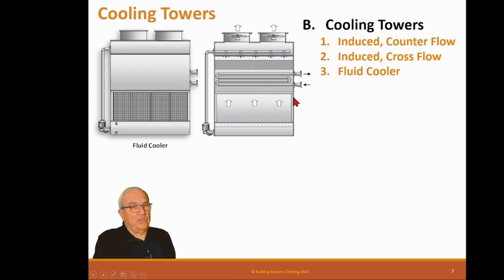So another way you can do this is you can actually put the heat exchanger out here in a flat plate heat exchanger and put some pumps. It seems like it'd be more expensive, but number one, it's 30% less operating cost. This heat exchanger and the fill adds more air resistance, so these towers are not as efficient. These fluid coolers are not as efficient as a tower. So you can save some money by putting a separate heat exchanger. Thus, you just use regular towers, so that's less expensive.